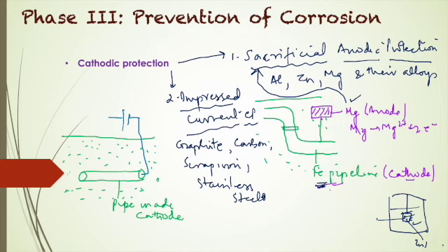Another metal which I have taken, let's say graphite or carbon or scrap iron or stainless steel, in backfill, I have connected to the positive terminal of the battery. When I do it this way, my iron pipe will start behaving as a cathode.